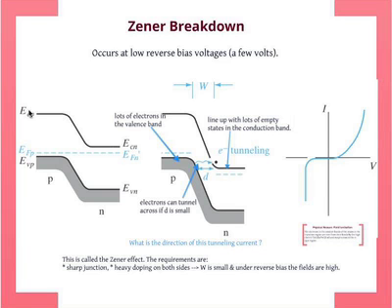So let's look at the band diagram. You have a conduction band and valence band. This is under equilibrium because the Fermi level is flat. You can look at a band diagram and that's another thing you need to be able to do: look at a band diagram and tell me what's going on. You should be able to answer that. This is equilibrium.